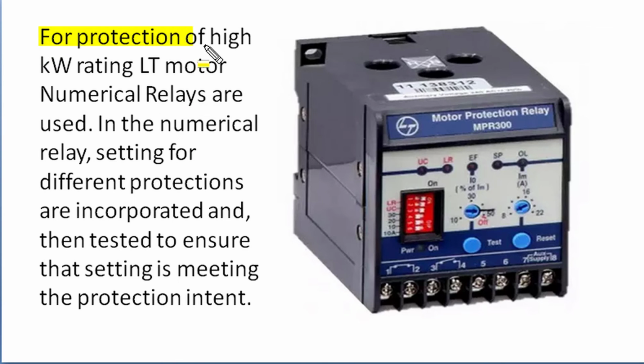For protection of high kilowatt rating LT motors or sophisticated motor drives, such numeric relays are used for all sorts of motor protection. In this numeric relay, settings for different protections are incorporated in its microprocessor programming, and such relays are tested to ensure that all protections are provided during motor operation. Most of such microprocessor based numeric relays are programmable and we can program them as per our protection needs.